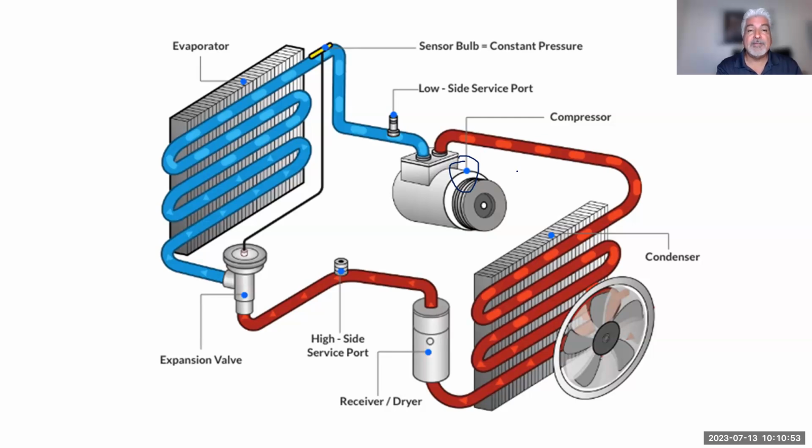So therefore, definitely want to put a voltmeter across that compressor clutch to make sure that it's not having a voltage drop, because the voltage drop is a way of understanding if there is high resistance causing low amperage going to that compressor itself. So please remember that. I cannot stress that enough. Make sure you do that. Just because you jump the relay and you engage the clutch doesn't necessarily mean you got a bad relay.